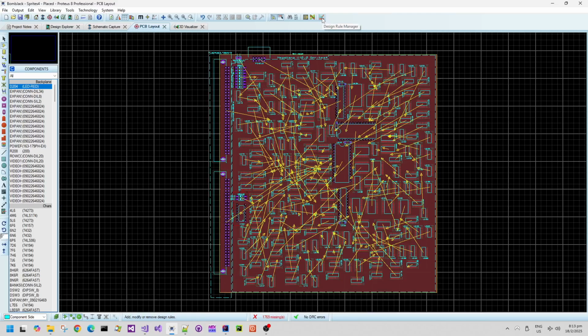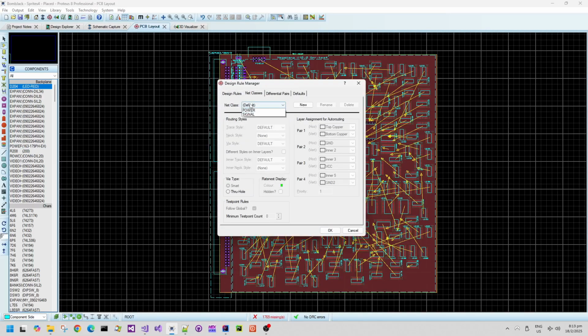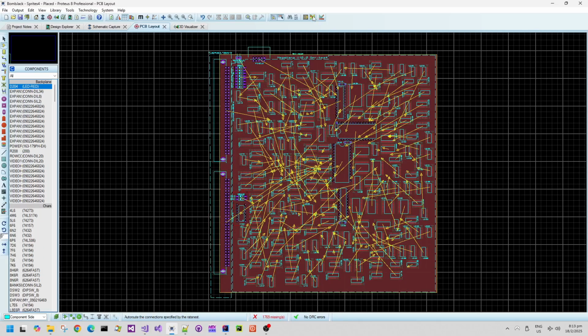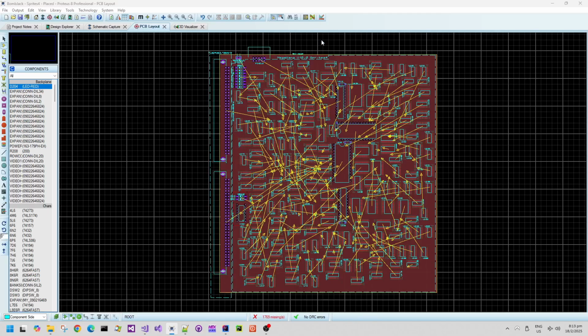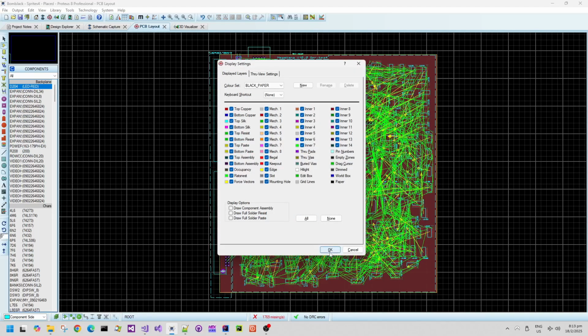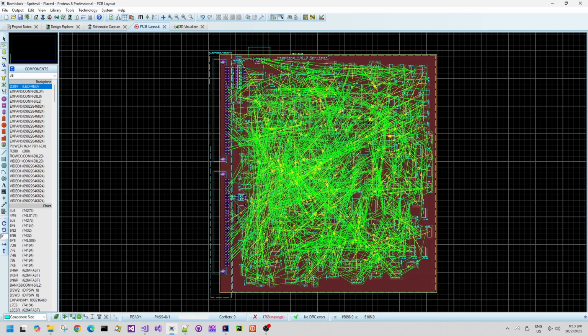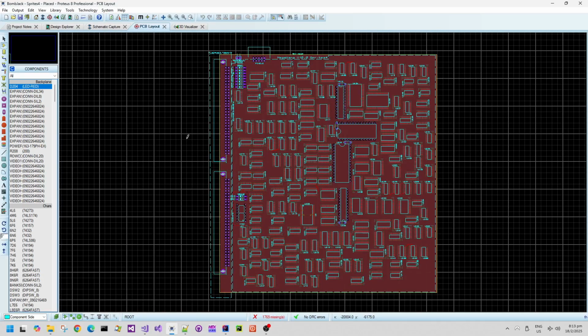Now, each of the layers, even though they are all tagged as signal layers, I did add some power planes, but the power planes can get chopped up by signals that get generated. So all of that looks good. I'm just double checking all of my settings. There's the rat's nest turned on, so we can see the green rat's nest showing the complexity and the density of the intended connections between the components.